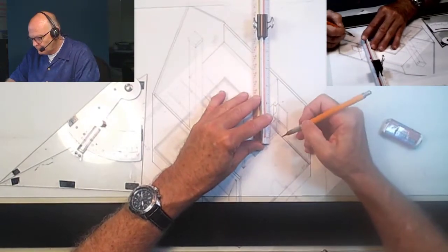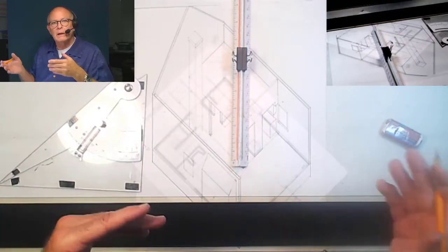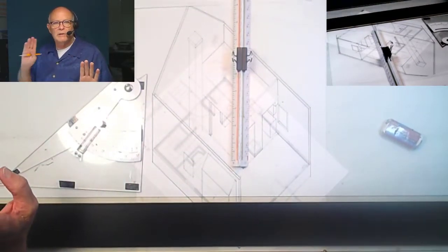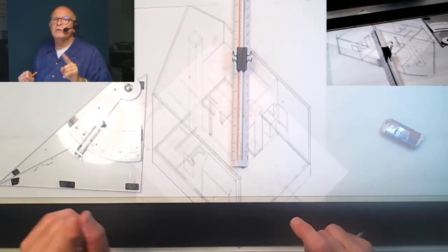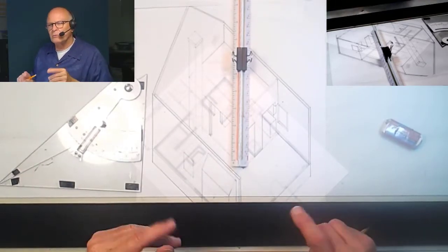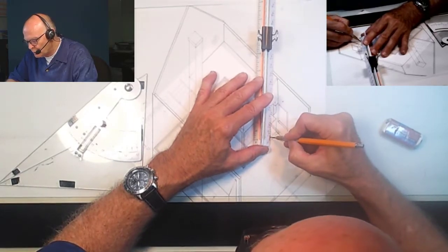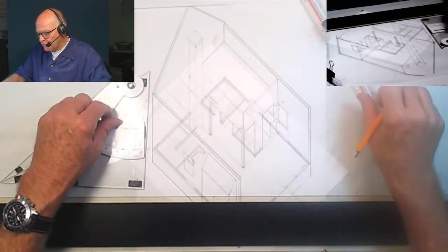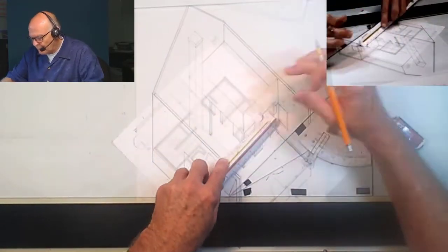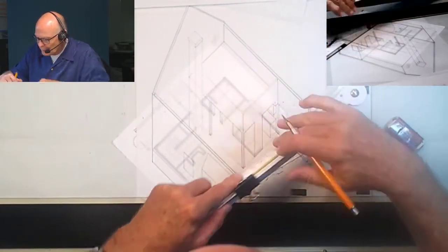That toe kick is 4 inches by 4 inches. So in order to do that, we need to put that in. Now the toe kick typically only extends in the front of the cabinet. It doesn't go to the side. But there still will be baseboard and some base trim that goes in there. So we'll talk about that in a little bit. But I'm going to go ahead and put in the 4-inch toe kick here. And it's 4-inch by 4-inch. So measure that one by that one. Sorry, by that one. There we go.